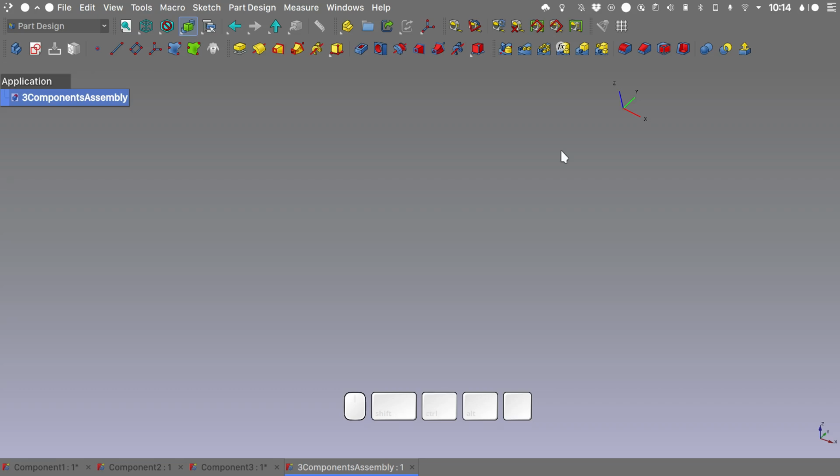And in FreeCAD, the most efficient way of bringing in geometry from external files is by creating links. A link in FreeCAD is a particular type of object that shares visual and geometry data with its linked origin, and you can basically see this as a clone, but has the advantage of having its own position, scale and material override. So with the theory out of the way, let's start by creating links of our 3 components in order to create our assembly.